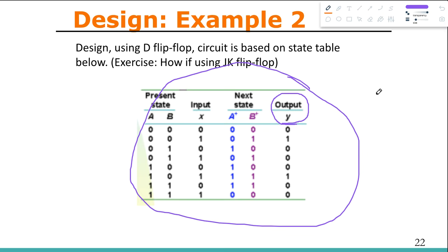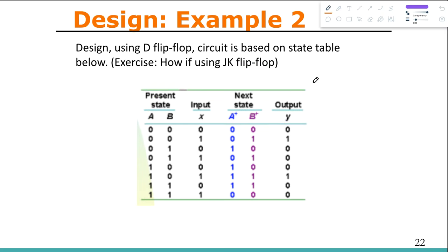So this would be the state table for that state diagram. Okay, so consider this is the state table, and from this state table in the next part you will create the flip-flop inputs. In this question you are supposed to build the circuit using D flip-flop. We can understand from this state table that there were 4 different states in the state diagram. So that means we'll need 2 flip-flops, right? 2 to the power 2 number of states, so we'll need 2 flip-flops. Okay, so 2 D flip-flops, and to distinguish the inputs among them we'll just consider them as DA and DB.